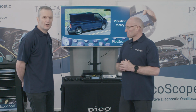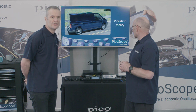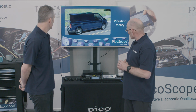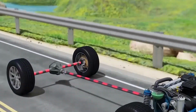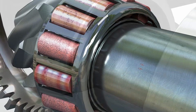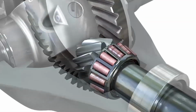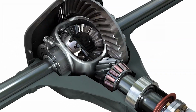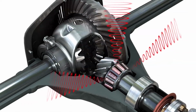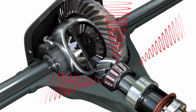Vibration theory, then looking at sound. So we talked about vibration being something that we feel, sound now something that we hear. They are one and the same. We experience them differently as humans. The animation here looks at a differential pinion bearing. Look at the condition of this bearing, how it's collapsed slightly, and now we have movement in the pinion shaft, and how the tooth contact between pinion and crown wheel is constantly changing, and the noise generated, as you can hear, is horrendous. And of course as road speed increases, so will the noise level.